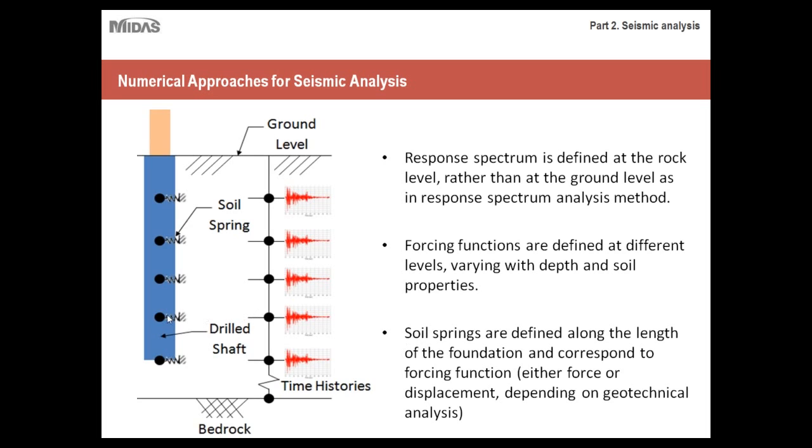The main purpose of these soil springs is essentially just to model the oscillations in your structure, as well as to model your seismic loading functions on them. So once again, these loading functions will apply a different seismic loading condition to each of these nodes and each of these springs, and therefore you'd be able to get a much more detailed and accurate analysis.